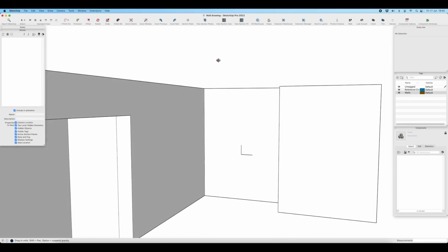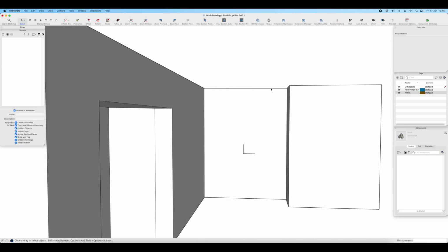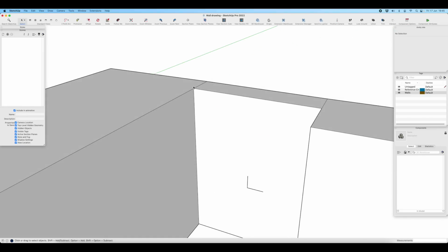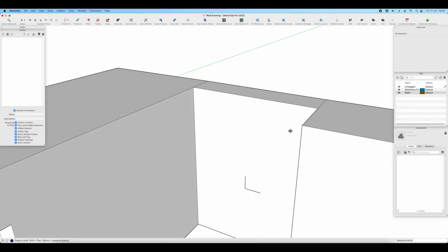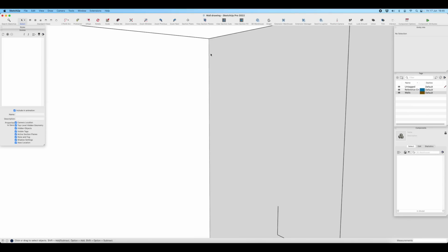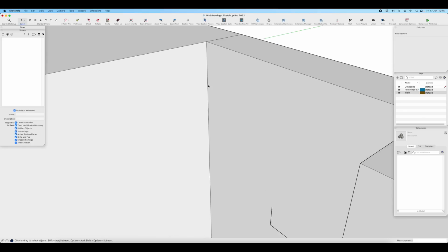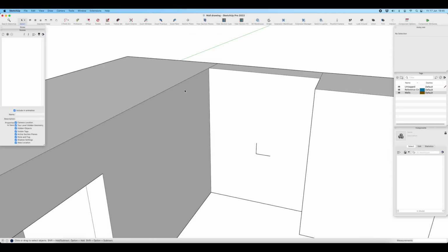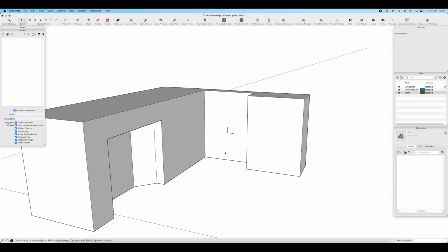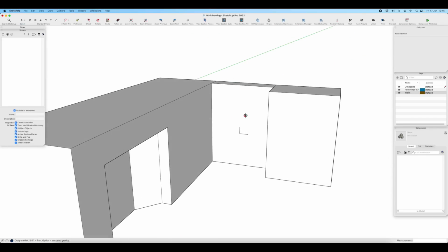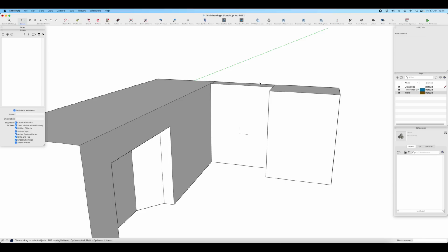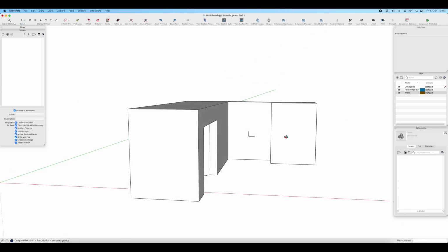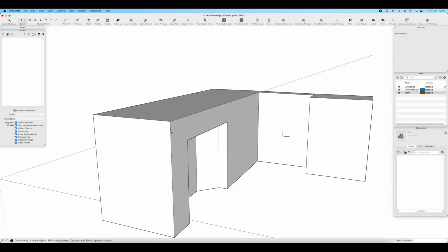Now if we do that in this out of level ceiling here, what that does is it tries to mitre the corner of the coving down and around on the angle, and it actually throws the underside of it out at an angle, or if you use your line around the underside, it throws the top of it out at an angle. So I like to draw everything like this out nice and square, then adjust it like we did here with that move tool. So I'd select this portion and move it downhill. So let's start by grabbing a section of cornice.